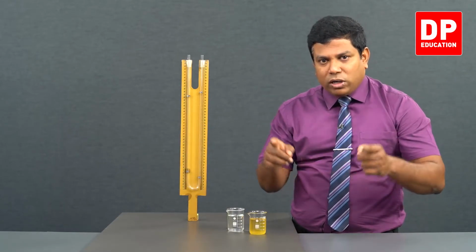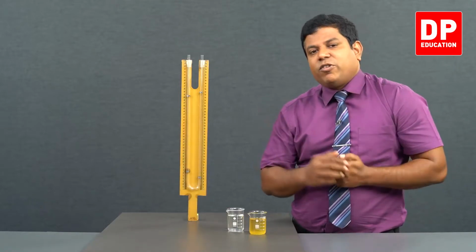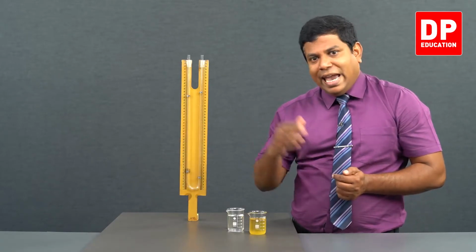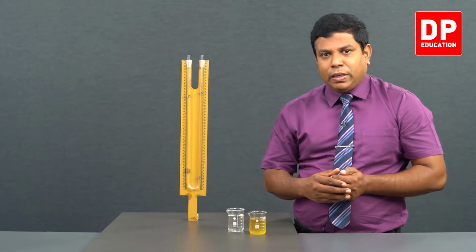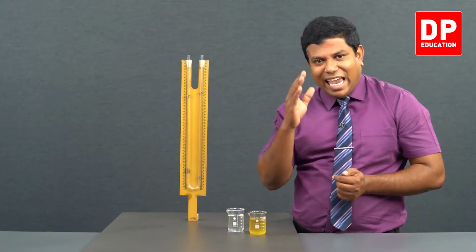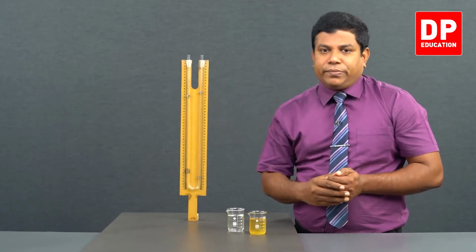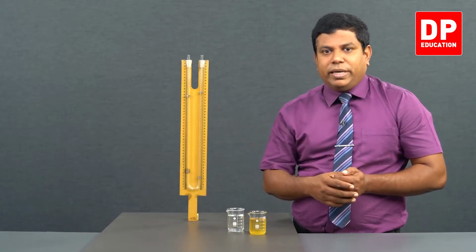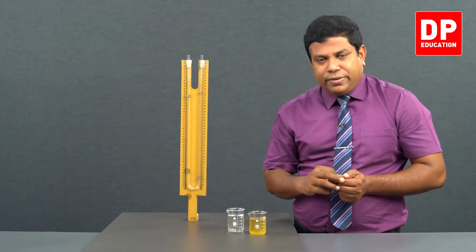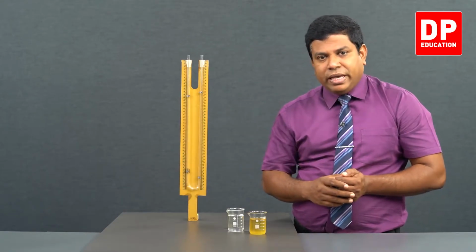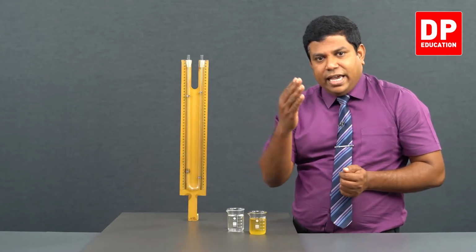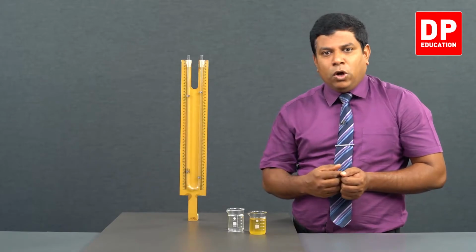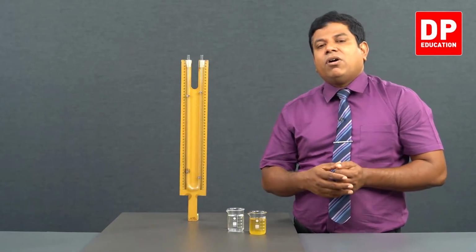Since both points are connected by water, continuous water, we can say both pressures have to be equal because they are at the same height, which means A plus H_O rho_O G and A plus H_W rho_W G will be equal. On both sides you can deduct A, then you will have H_O rho_O G and H_W rho_W G. G can be nullified, then what remains? H_O rho_O and H_W rho_W, both will be equal. So, if I can measure the oil's height and the comparable water's height, H_O and H_W will be known, then I can say H_O over H_W, or the other way around, H_W over H_O, will be equal to rho_O over rho_W. Rho_O over rho_W is what we call relative density of oil.